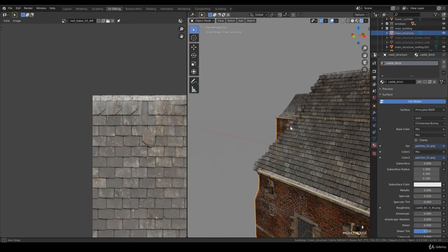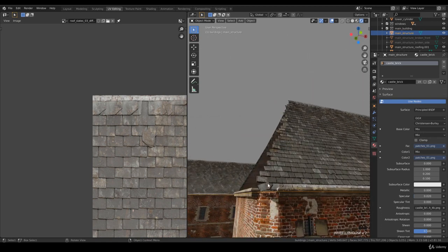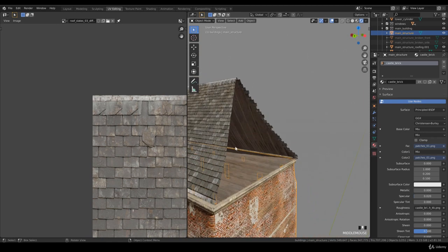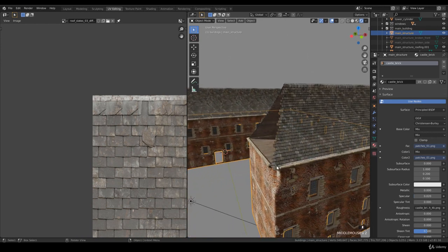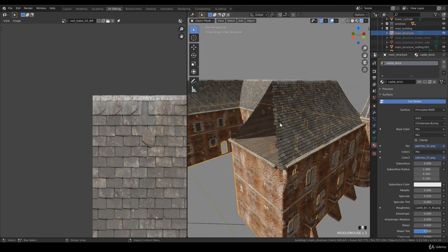Alright, I completed this side of the roofing, and it adds a very nice detail when you have all sort of separated roof tiles. So of course we need to have these ones also on the other side. So my question to you, because you learned this already in chapter 5 with the farmhouse, copy these and rotate them so you can stick them on the other side and try to match it with the other roof tiles. If that's too hard, you have to do it one by one, but it's a sort of exercise because it's important you try this yourself. So we'll pause the video, and good luck.